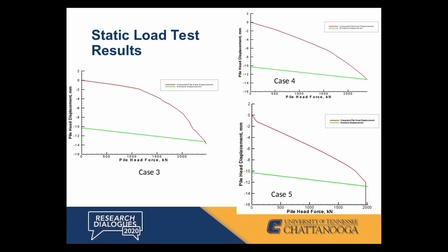But with case 5, we have a straight drop off, whereas with the other two, it's more gradual, and that's something that characterizes the static load response in STADYN from the very beginning. Virtually all the cases have a more gradual drop off. Case 5 is not necessarily the first time, but is one of the first times, particularly with actual data, where we see that. And it's the only case that actually replicates that part of the actual results.